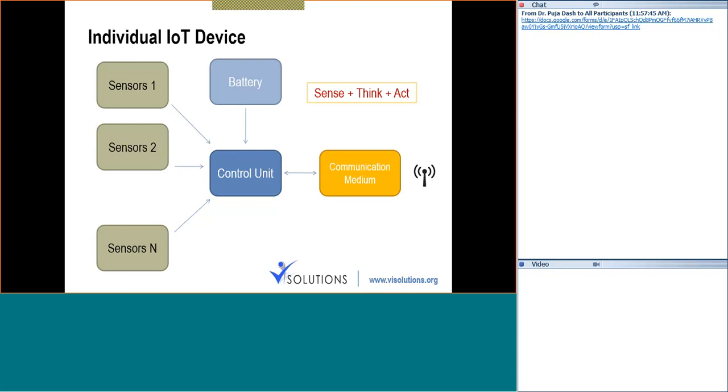Let's say some fault occurs, and due to the fault, the current level rises. Instead of sending this data to a remote cloud and having that remote cloud make decisions, some decisions should be taken instantaneously, like operating a relay. In that case, the control unit should also be able to take some decisions, but only the critical ones.